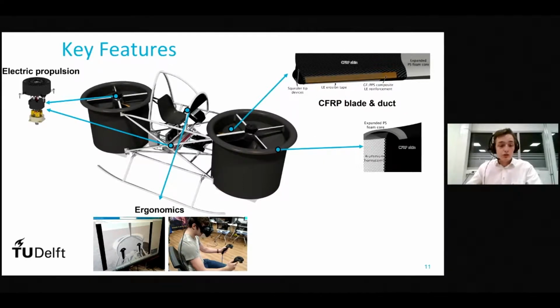So we decided that the rotor and duct should be made from composite, to improve the stiffness, reduce the weight, and improve the manufacturability. The complex shape here can be made by machining a foam core and hand layup around it. The duct lips are also cored with milled foam, whereas the duct walls, because they need even more stiffness, are made of a honeycomb core. So we went for a ducted design for the reduction in tip losses as well as for safety and stability.